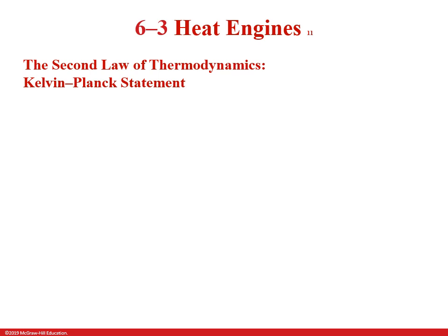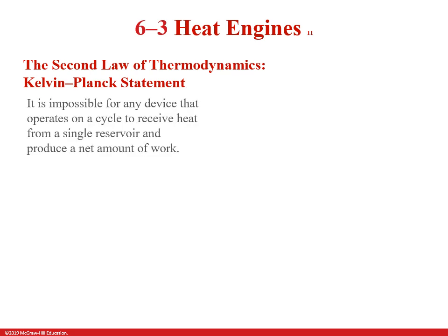All right. Finally, let's look at the Kelvin-Planck statement that's applicable to heat engines. Kelvin and Planck came up with the thermodynamic principle that it's impossible for any device that operates on a cycle to receive heat from a single reservoir and produce a net amount of work.